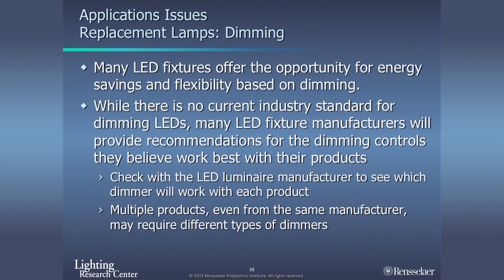And these are some other dimming profiles with the same problems, where you're dimming down and you have all different funky things happening with the lamp. People aren't liking that. And the reason for that is that the triac dimmers that are used are not really meant for this. They basically chop the AC wave. And that was great for an AC light source, but it's not great for a DC light source with an electronic driver. And so what's happening is there's a lot of incompatibility between existing drivers and replacement lamps or new